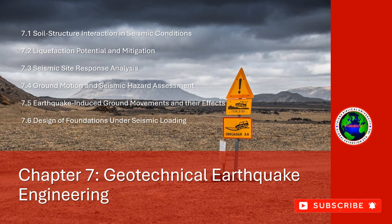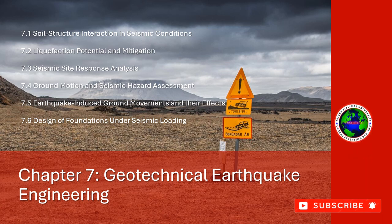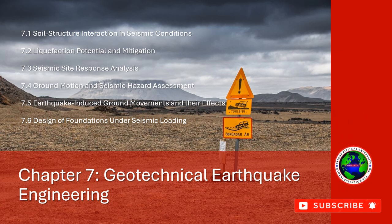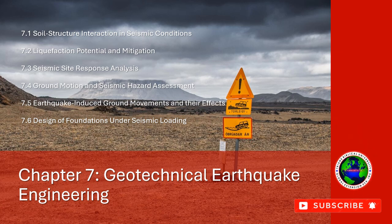4. Retrofit and rehabilitation of existing structures. For existing structures, site response analysis can be used to assess the need for retrofitting or strengthening to improve earthquake performance. If the site response indicates significant amplification of seismic waves, the structure may require upgrades, such as base isolation or foundation reinforcement.